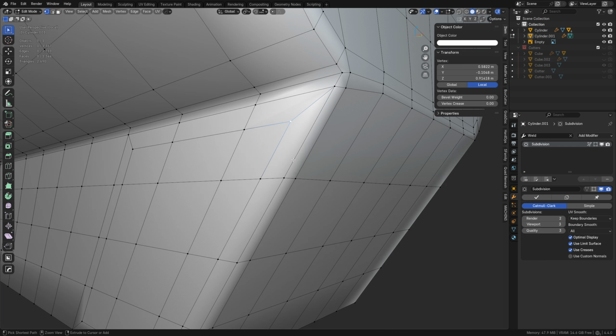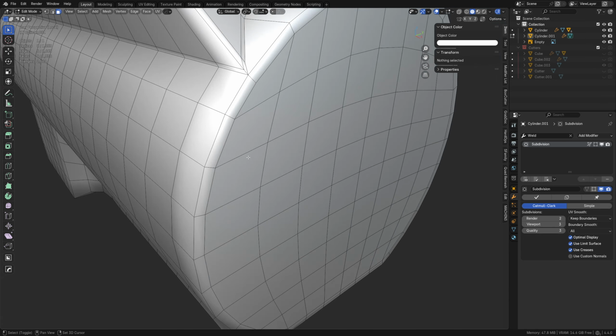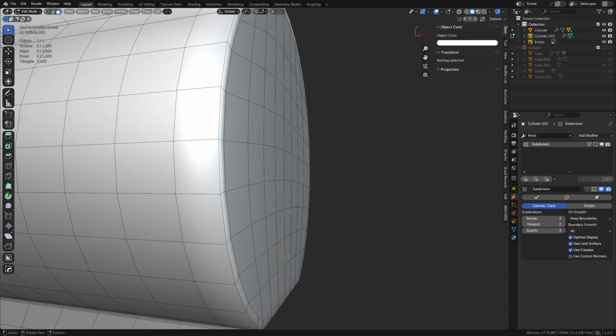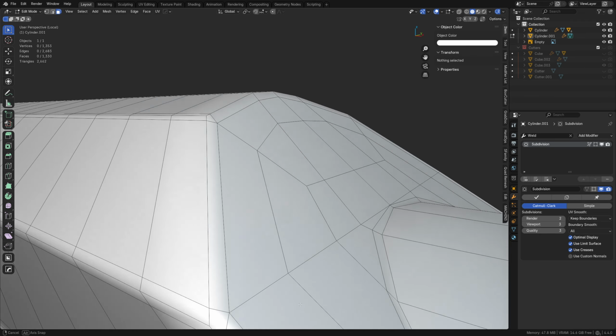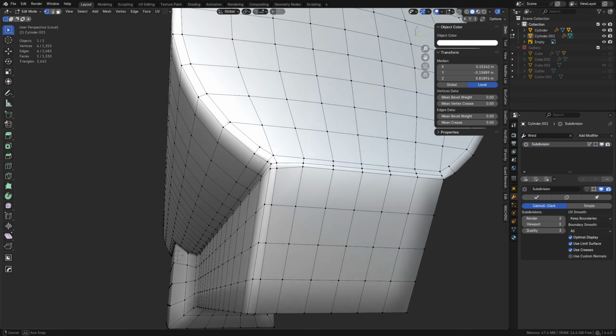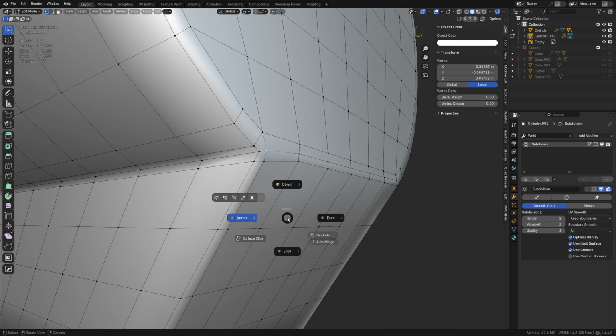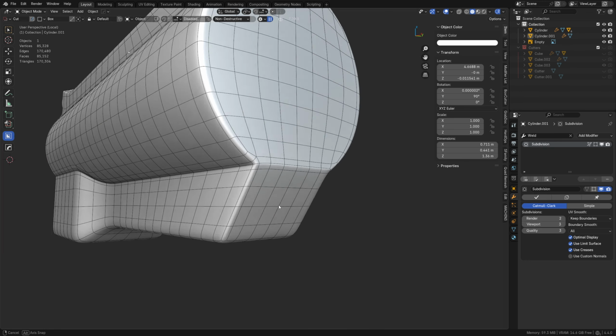These poles, these are your redirect poles. Once you understand that and how you can break certain ones, like convex shapes, you can break into this kind of a shape here where the triquad works really well. And then that's convex, and then concave you do where they fan out is typically what happens there. But you can do it, and it's super useful.